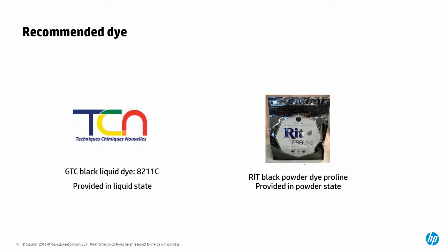The recommended product to use from the Reed company is the Proline series, the one that you can see in the slide, because this is the one that we have proof is giving the best color homogeneity. These dyes, the Reed dyes, come from the textile industry, but as Multi Jet Fusion is printing with nylon, they can be used to color our parts as well.